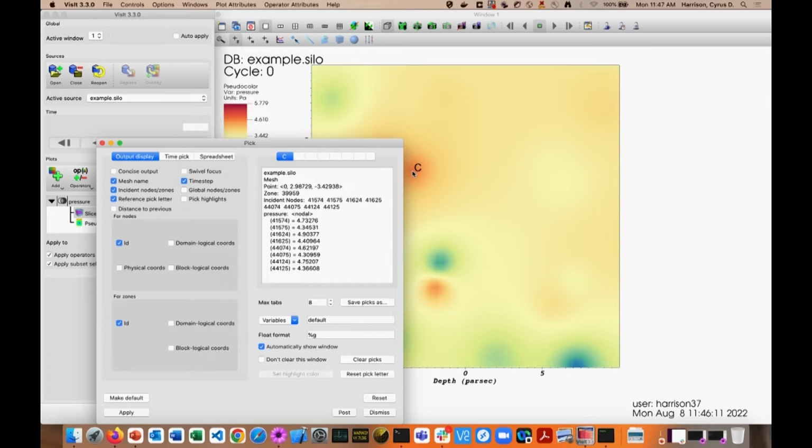There's some other different options you can turn on that aren't by default, but what's useful here is, hey, you clicked at this point in space. This is actually a nodal data set, so it's associated with the vertices or the points. You can think about it that way. So it's showing you for that cell all of the values for that. So this is highly detailed debugging information that's very useful. Like if you have a mesh tangle, usually you're going in there and asking questions about this.